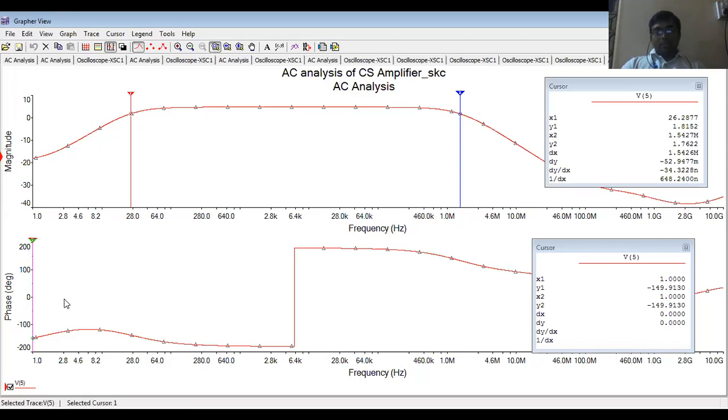In a similar fashion, you can observe the phase diagram. With the two scales, the first scale is at the minimum value. As we increase the frequency and it reaches near the operating frequency, your phase shift is nearly 180. Y2 represents the phase shift. Here the phase shift is about 155; it becomes 175 when x2 is nearly 1k, and 178, near 180 degrees.